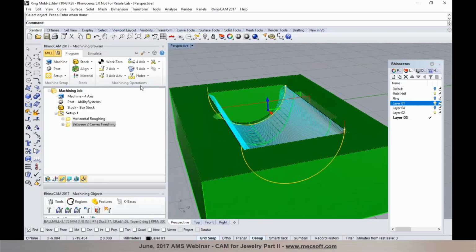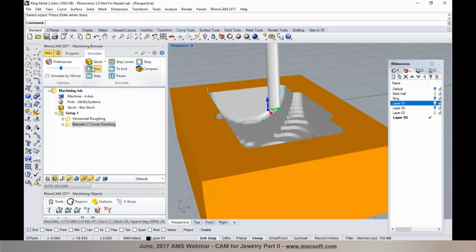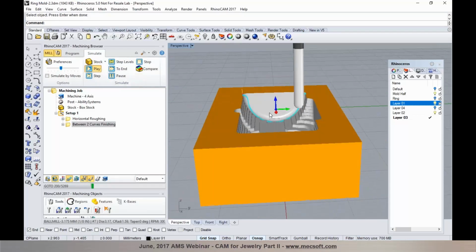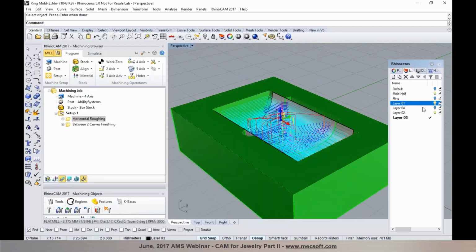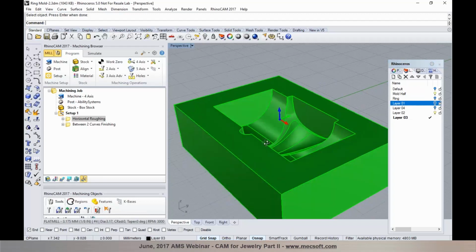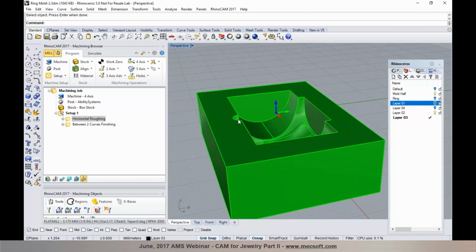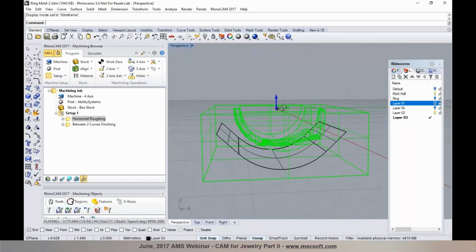Again, you're just programming in a 3-axis mode so that there's no rotation axis involved in here. Now, rather than programming this as a 3-axis, we would like to use a 4-axis technique to program this, which I'm going to show to you here in just a moment, how we can take advantage of the 4-axis drive surface machining operation. Now, in order to program a drive surface machining, I need to have a surface that's normal to the axis of rotation. So in here, I've actually created a surface, and as you can see, the surface is beneath the part.